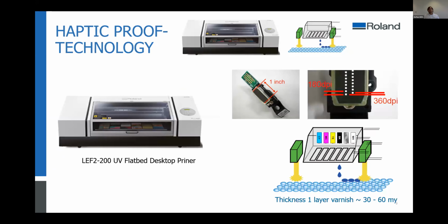So now let's go into detail. I will explain to you how the process works. I will in general explain how digital inkjet printing is working. In our case, that's very easy. So what we have is actually a table moving from the back to the front. And we have a printhead scanning from the left to the right, spitting at the same time ink on whatever object is lying on the table. That's the basic principle.